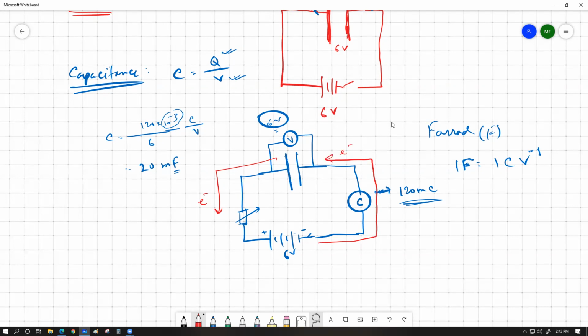And one thing is very, very important: a battery does not actually create charge. Using chemical energy stored within a battery, it only dissociates equal amounts of opposite charges, which means you cannot simply take some minus 10 coulomb charge out of a battery or minus 1 coulomb charge out of a battery. If you want to take some minus 1 coulomb charge out of a battery, you have to feed plus 1 coulomb charge from the positive side. A battery on its own is an altogether electroneutral object. So inside a battery, the total number of positive charges, protons, and the total number of electrons are usually pretty much the same. To avoid confusion, we're going to say they're exactly the same.